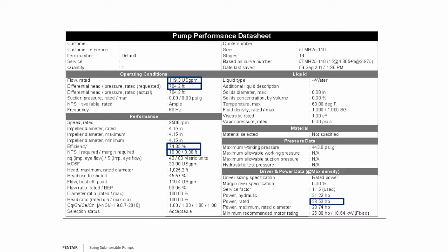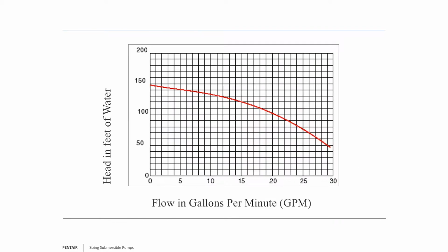Now, we have our data sheet. We have very good numbers that we got from that pump. One thing I want to emphasize: when you're talking about a synchronous speed motor running one fixed RPM, you'll have a hard data output. Now, this is a much lower flowing pump in gallons per minute, but if you see here, this pump builds a maximum of 148 feet of head, and its run out is roughly 29.5 gallons per minute.